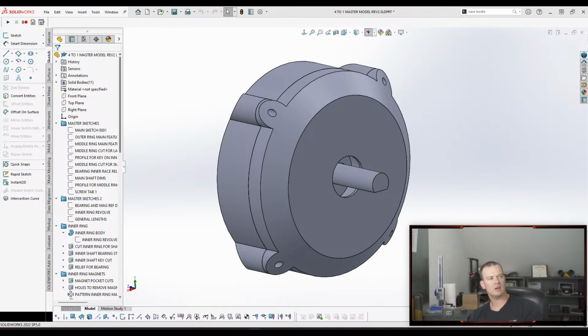I think the only slight advantage would be that unless you're sharing surface models using the master model technique, if you're not doing that, part of me says go skeleton sketch, because then the likelihood of you needing to get in there to change geometry is lower.